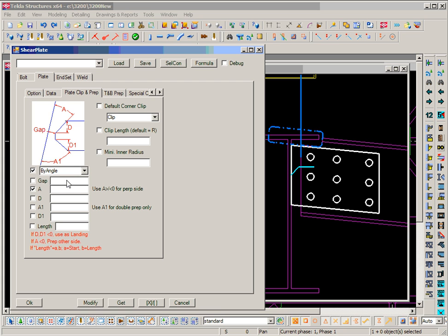And remember, you can always use a formula. For example, you can use tube depth plus ½ inch minus depth minus ½ inch. Then it will go through the whole tube depth and extend by ½ inch on the other side.